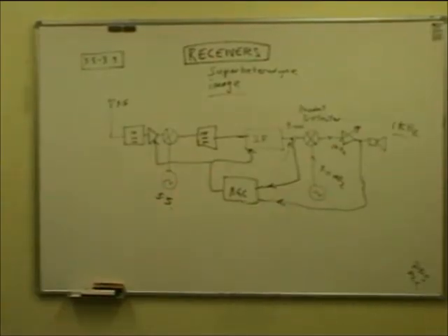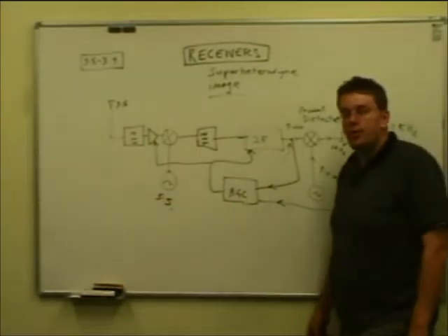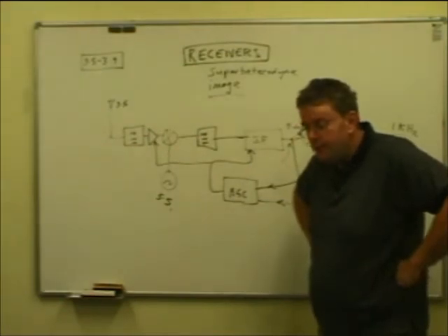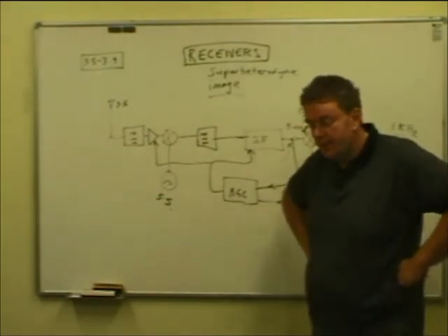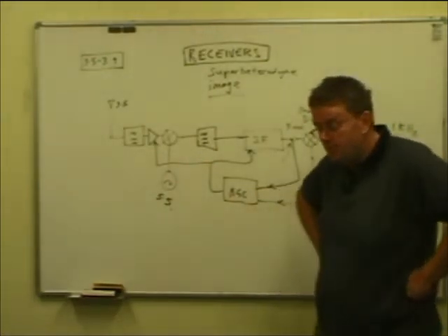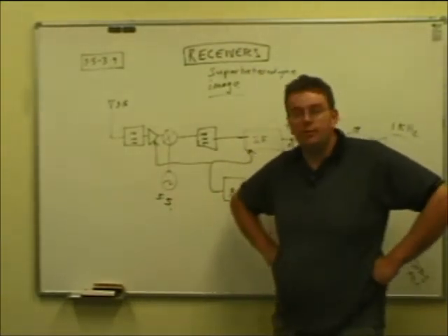The design of good automatic gain control systems in better quality receivers is quite sophisticated. They'll have quite fancy systems there to cope with the conditions they're exposed to. When you're receiving AM, it's quite easy because it doesn't matter if anyone's talking or not. There's a carrier there to tell the receiver how strong the signal is.